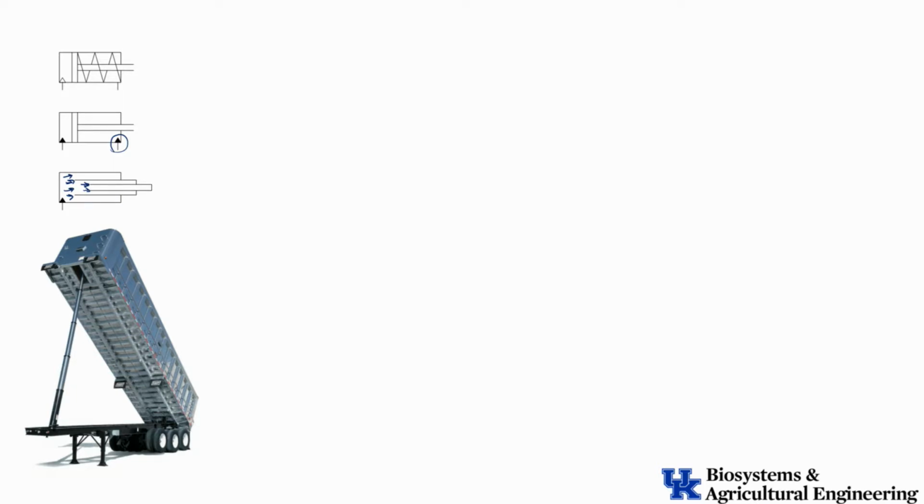It also helps me keep from lifting heavy loads too high. We'll do this on forklifts, for instance. If I've got a load on a forklift, I can lift a pretty heavy load to a certain extent, but once I start getting to these subsequent sections up here with a smaller diameter, now I can't lift as much, and that keeps me from lifting loads that are too heavy too high in the air, to increase the stability of the vehicle.